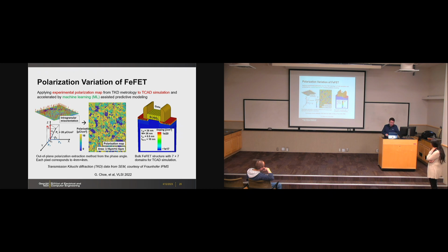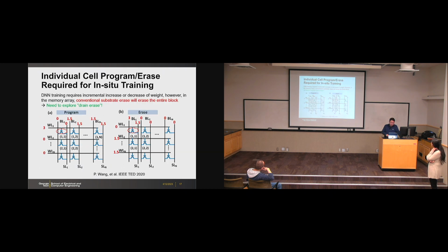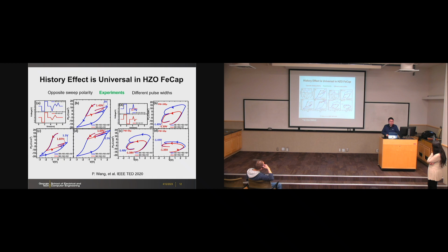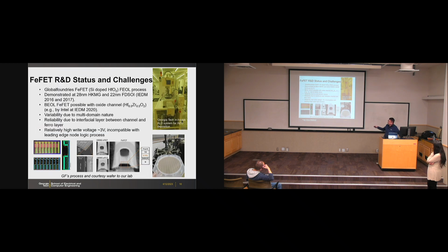But for the industry's roadmap, there are two near-term applications. The first one is of course eFlash replacement. This is what GlobalFoundries is positioning this technology for at 28 and 22 nanometer, to replace the embedded flash. Because in embedded flash, you add many masks to integrate that.